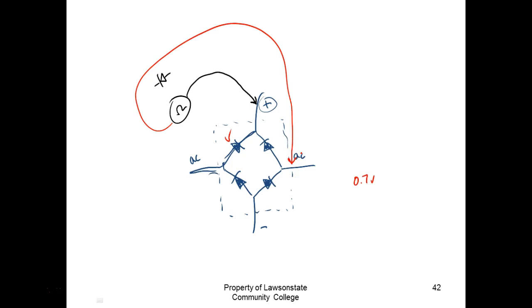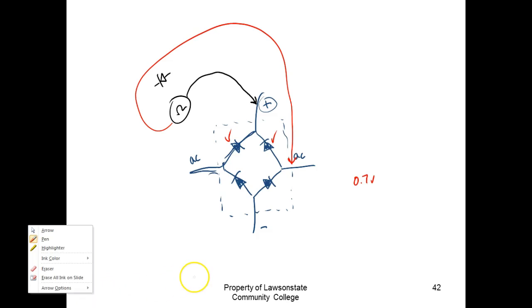So which diode are we checking? That's on the top, right? So we're checking that guy right there. Okay. Now what I would probably do next is, guys, we check them if they're forward biased. We need to also check them if they're reverse biased.